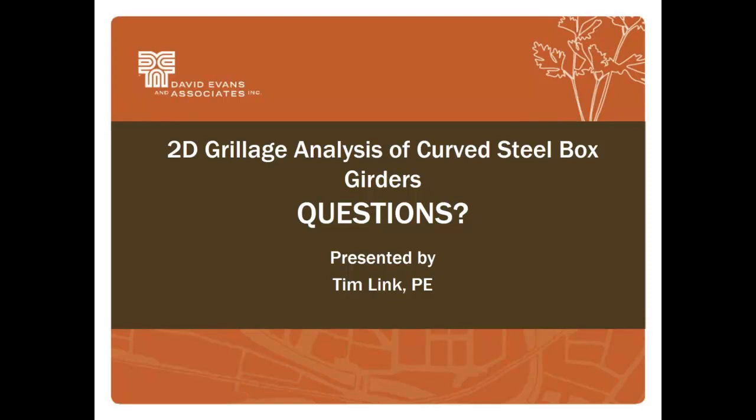It wasn't really needed for necessarily the overall stiffness of the model. The stiffness of the barrier element compared to the steel box girder section is pretty minimal. And the other part was, was it used for the structural capacity?